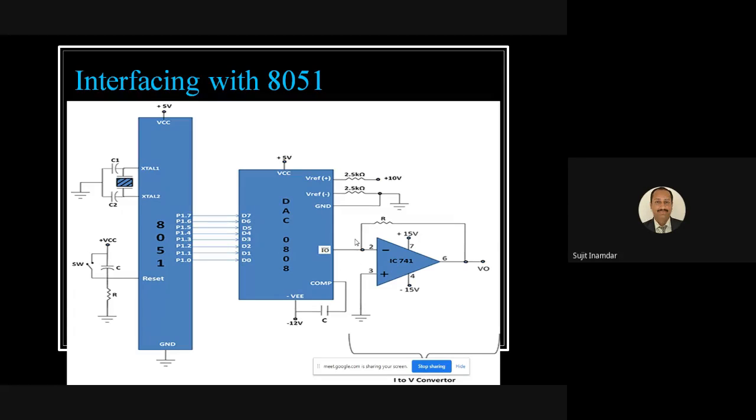Okay, let us continue. Here the different circuits use different techniques and different methodologies to achieve the output. Here they have used the IC741. Some other ICs are also available, so that also can be used. We will see that at the time of the actual simulation. If you are looking at the left side, those are the normal default connections that are required. That is the crystal, supported by C1, C2. It is 1 microfarad, 1 microfarad.